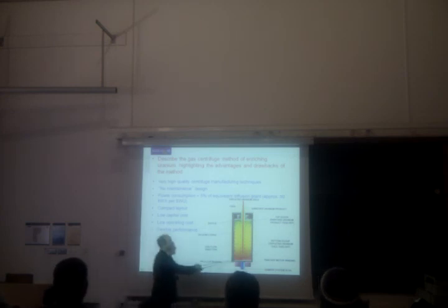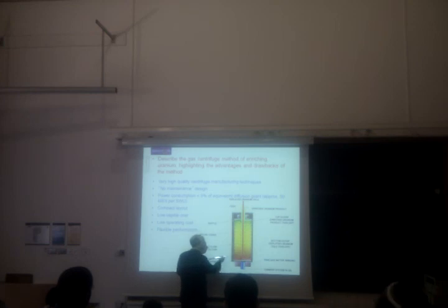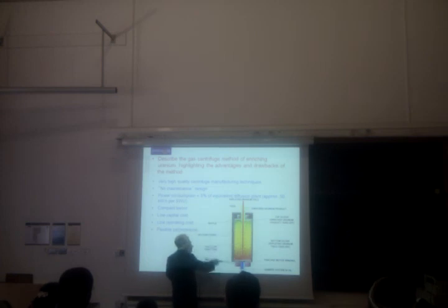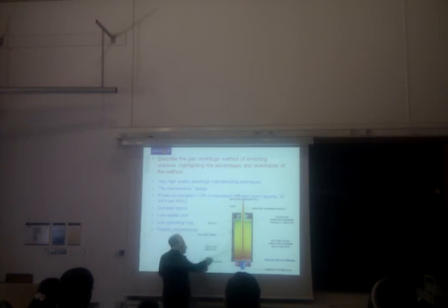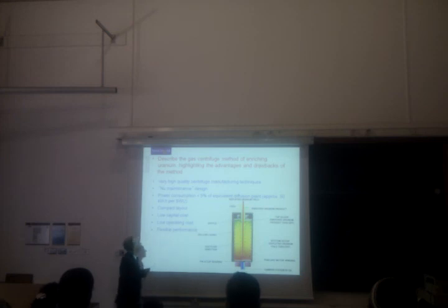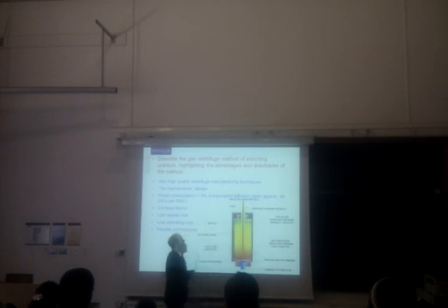You can indicate that there's a thermal gradient as well, so we've got both a mass separation where the heavier isotopes progressively move towards the outside of the centrifuge, and the lighter isotopes, the ones we want, tend to come to the middle. But we also got some thermal gradients axially, and again we get the lighter stuff tending to move towards the top, heavier stuff tending to move towards the bottom. So the enriched product that we want tends to move towards the top of the centrifuge and towards the middle here. The top scoop is the enriched uranium product takeoff.